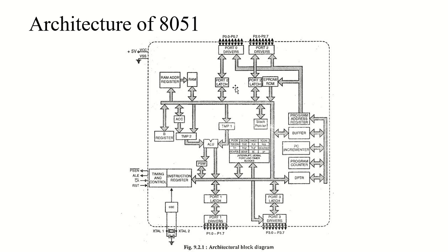So some of these registers are bit addressable while the remaining are byte addressable, and some of the addresses, like locations between 80H to FFH, are not used at all, and if we try to use these unused locations that are not defined or are empty, then we may get unpredictable results.